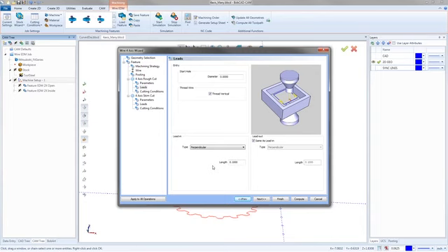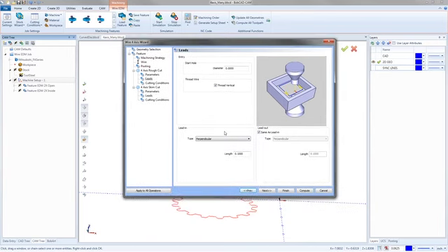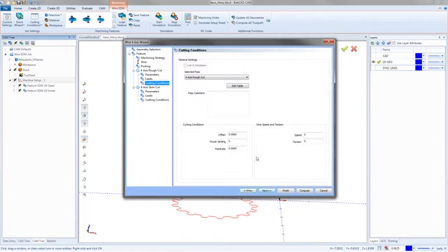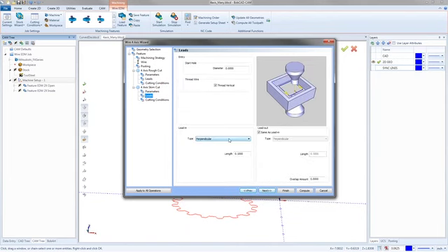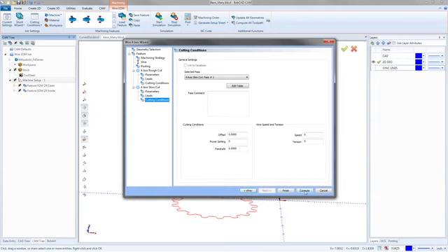That's the difficult part. I didn't put a point on this one. I really should have. I'll come back and add a point in a minute, but I'll use the perpendicular for now. The benefit of having a point, especially on a fourth axis, is that you're going to feed that wire to the same point, and then the wire is going to move to its position and put itself in the correct position for us. So I like to use a start point usually for my leads, but no big deal here. So then we get the parameters. So I'm, again, only doing one skim pass, machine comps on, and no stop points even selected. Leads, perpendicular, again, that's fine. And when we're all done, we can hit compute.